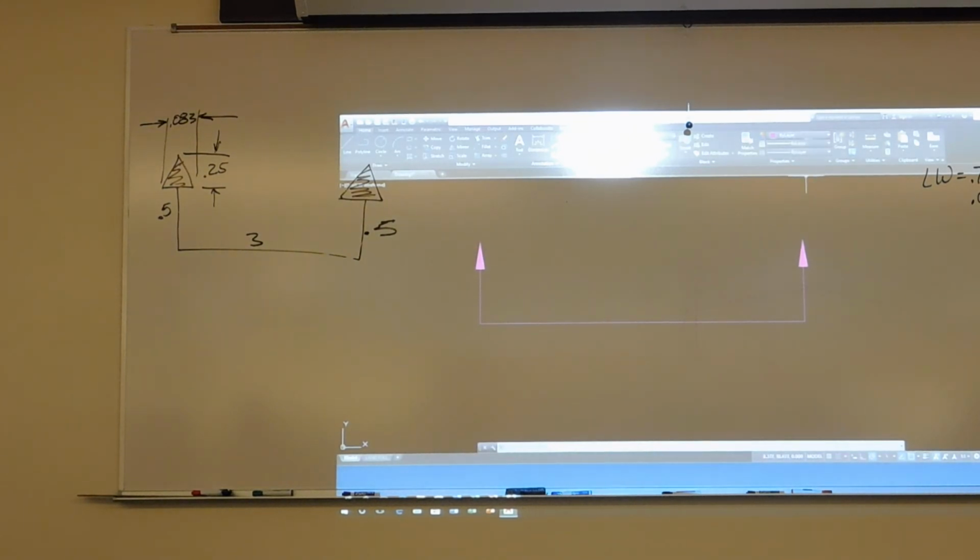On the home ribbon, you have this little properties section right up here. Now, if you change anything on here and run with it, it overrides your layer. So I kind of discourage using this because you forget about it, and then all of a sudden your lines are all on the viewport there, and none of them are plotting, you wonder why. Well, you accidentally had that set and you forgot to set it back. I just know, for me, cutting plane lines are one thing I always change the property on. But I only do it for like 2 or 3 things on my entire drawing status. So you want to be a little careful.